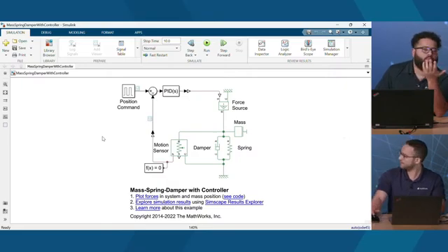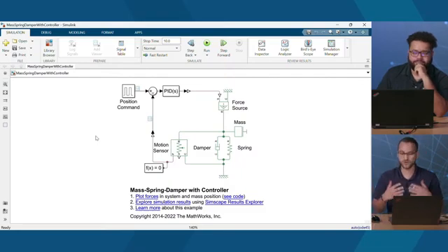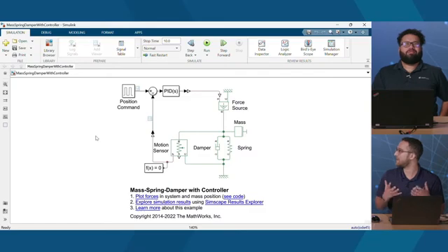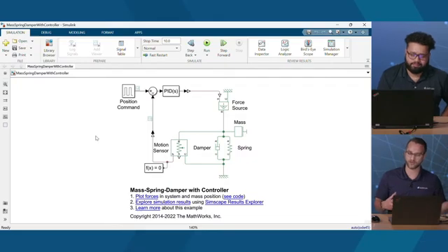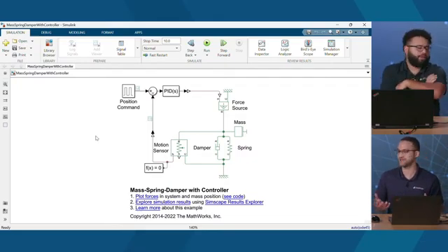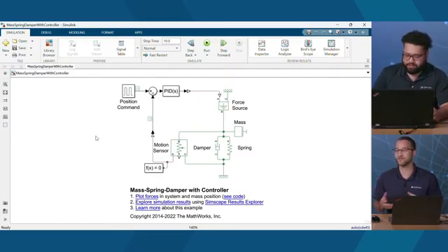Right. Yeah. What is a use case when you'd use, say, Simscape over Simulink? Right. So if you have a really complicated system like a spacecraft, and you don't know how that spacecraft is going to behave, but you know what the components are made out of, you can start building out your Simscape model to be able to create a representative model of what that is without needing to know all the underlying equations. We call this physical modeling because you're putting together pieces representing physical pieces, with physical equations under the hood, rather than having to figure out what all of the mathematical representations are, which can be a pain.